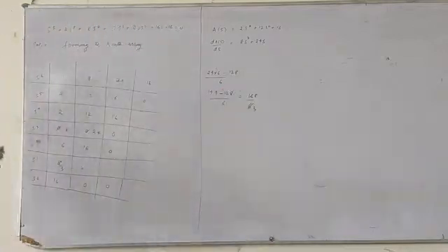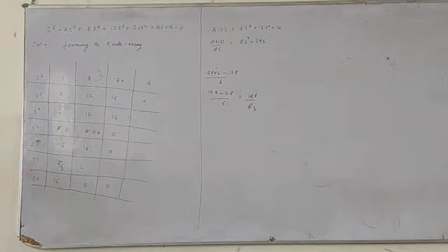Okay, so now again, if we talk about the investigation of the stability, there is no problem, there are no sign changes in the first column. We can say this is positive, positive, positive, positive, positive, and positive. So when there are no sign changes, there are no roots on the right half of S plane, the system is stable. So this is a very simple concept. But there is something more to be discussed here.